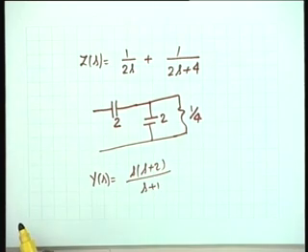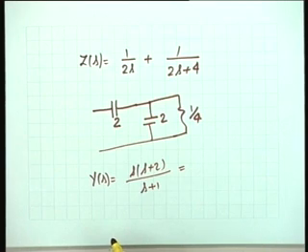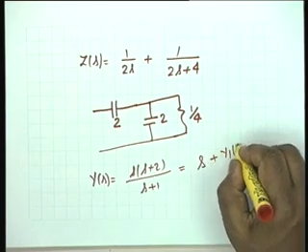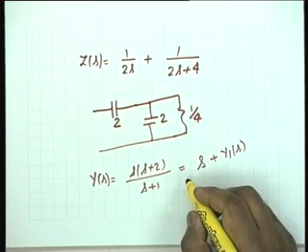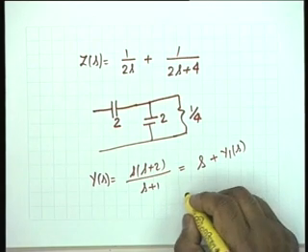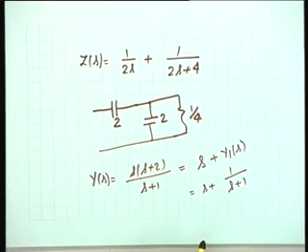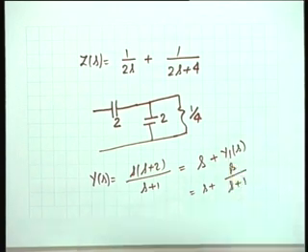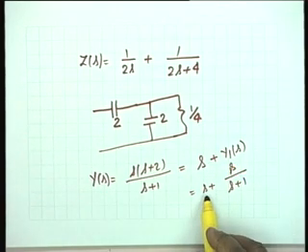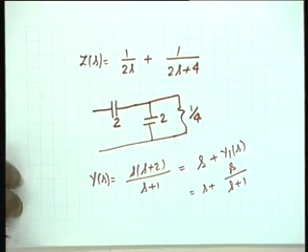Obviously this has a pole where? On the j omega axis. You see, you have to remove poles on the j omega axis only, no real axis. Now it has a pole at infinity, and the residue at infinity is 1. So it is simply s plus Y1 of s. Now if you remove s from here, what is Y1? It is s by s plus 1. Is that correct? Yes, that is correct.